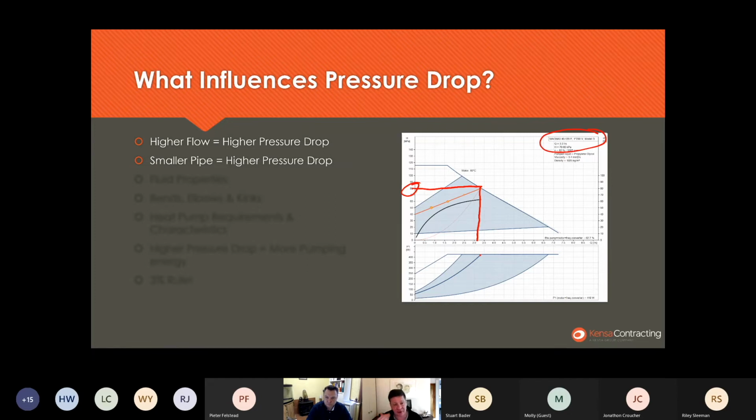And if we are looking at, say, a block of 20 flats, or let's say 10 for easy counting, a block of 10 flats, if we were designing it for all those 10 flats running all the time at optimum flow rate, you could say we would be over designing the system. So we can take a rational view and say, well, actually, if 80% of them are running, then let's design it to that maximum flow rate, so if 8 units are running, let's design it to that optimum flow rate. But if more than 8 are running, let's drop it down so that when 10 are running, we're at 80% of that flow rate. So therefore hitting the minimum on that unit.